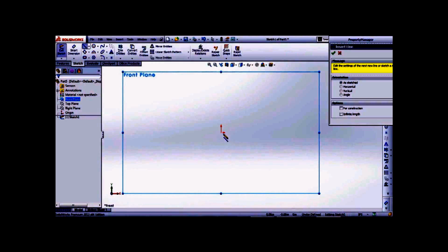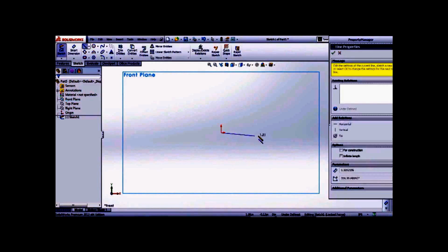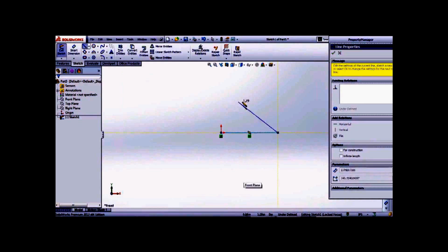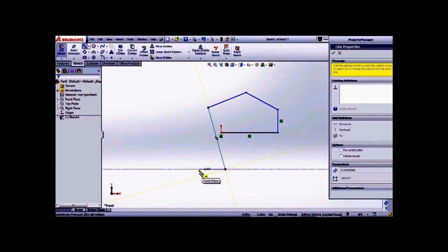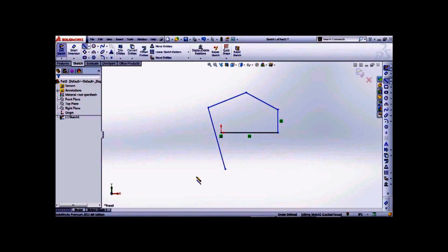So to start making a sketch, I can make a line. And I just click and I can move my mouse wherever, and the second point that I click will finish the line. And it gives me the option to make another line on my endpoint. So I can make another line, another line, and another line. If I want to stop making lines, I just double click and we have some lines.